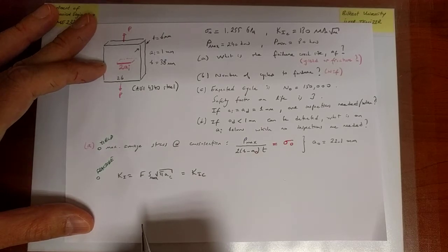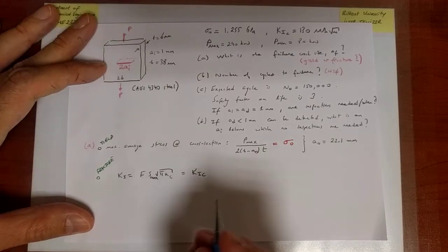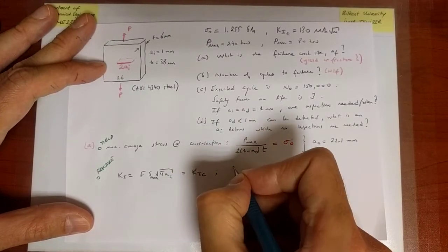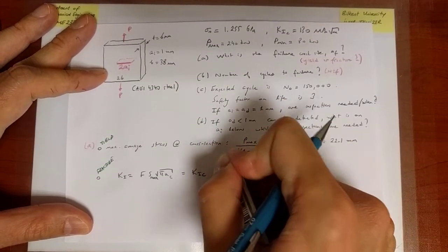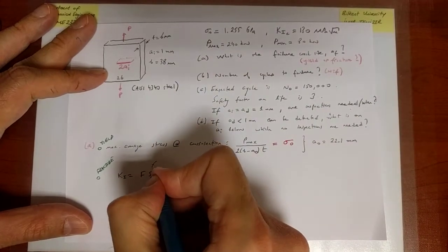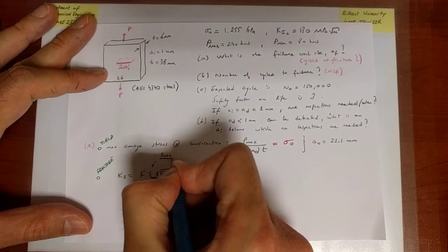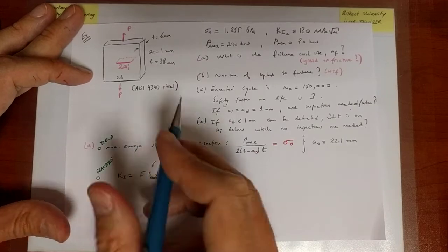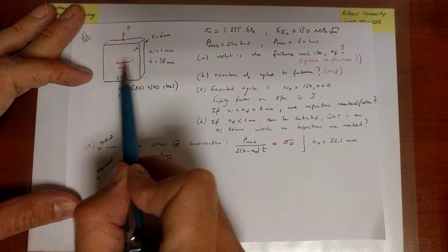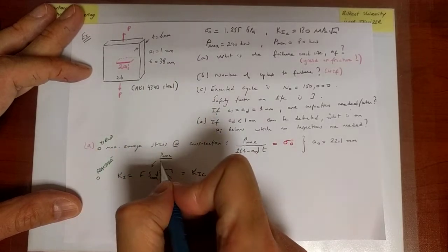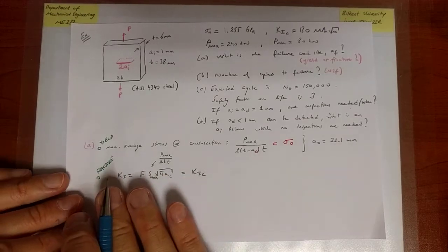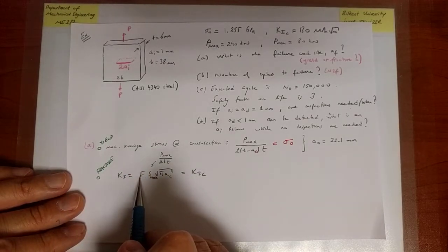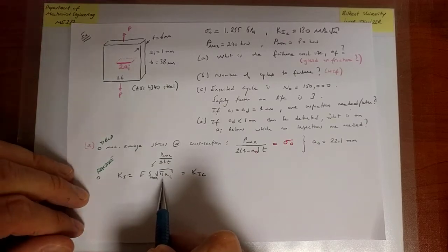Now, the definition of S max, remember, is equal to P max, a tensile load, the maximum tensile stress at the cross section where the crack is present, omitting the presence of the crack. So it is, in these cases, always equal to P max divided by 2BT, that's the area. So here, the material parameter is known. I don't know F, I know S max, I will try to solve for AC.